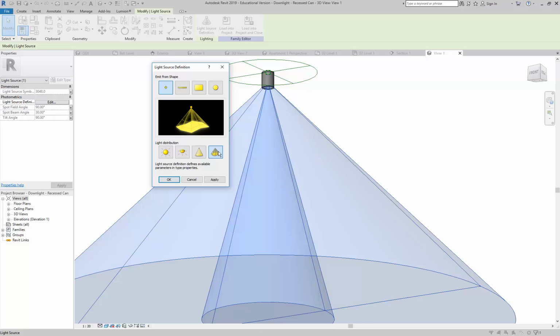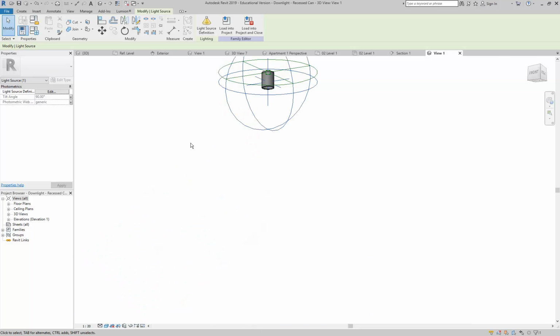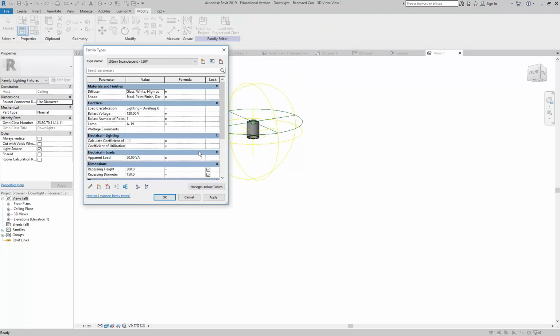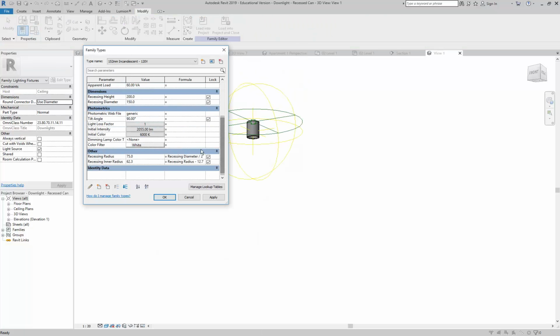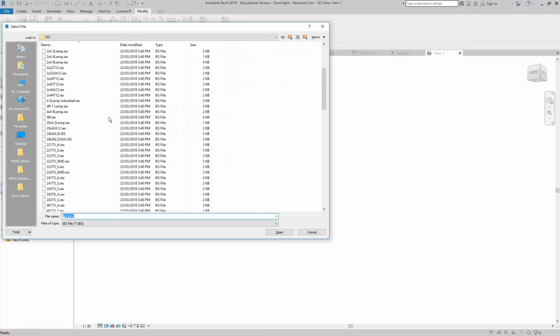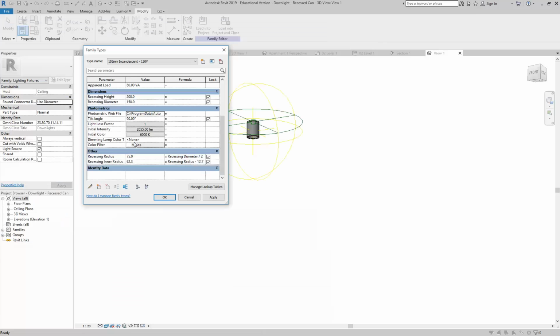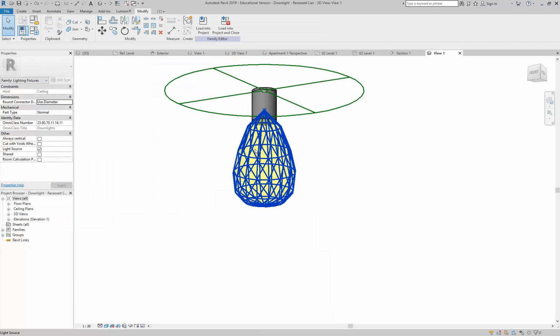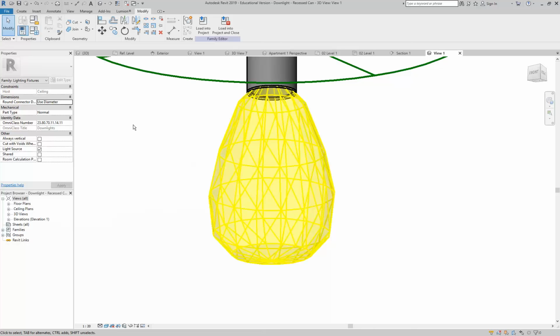So once you know about it, you can do that, and maybe it's a quick thing I can show you. So once you choose Photometric Web, go into here, and you can set the ones with Revit as well, just like V-Ray. They do give you a few IES files to get you going. Here, that's where you set them. And so here we've got some different distributions. And so here goes Spot Ideal. So that's a type of spotlight. So I've just loaded that. And there we are. So that shows us a bit of what the distribution looks like.